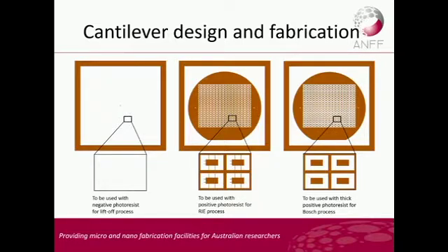And then from the back, we need to define how we're going to etch, because what we're going to do is etch the cantilevers from the top, and then etch all the way through the back. So we need a mask to define front and back. Okay.